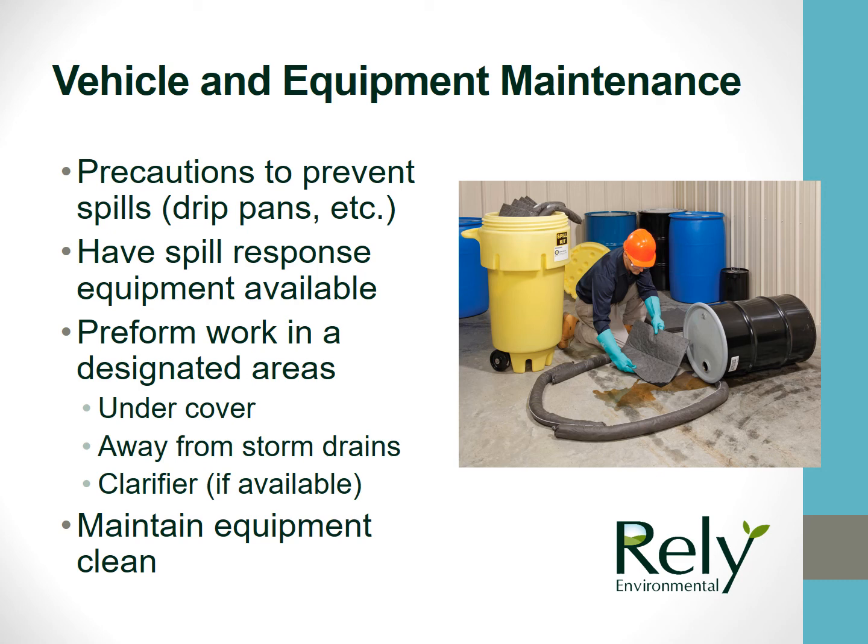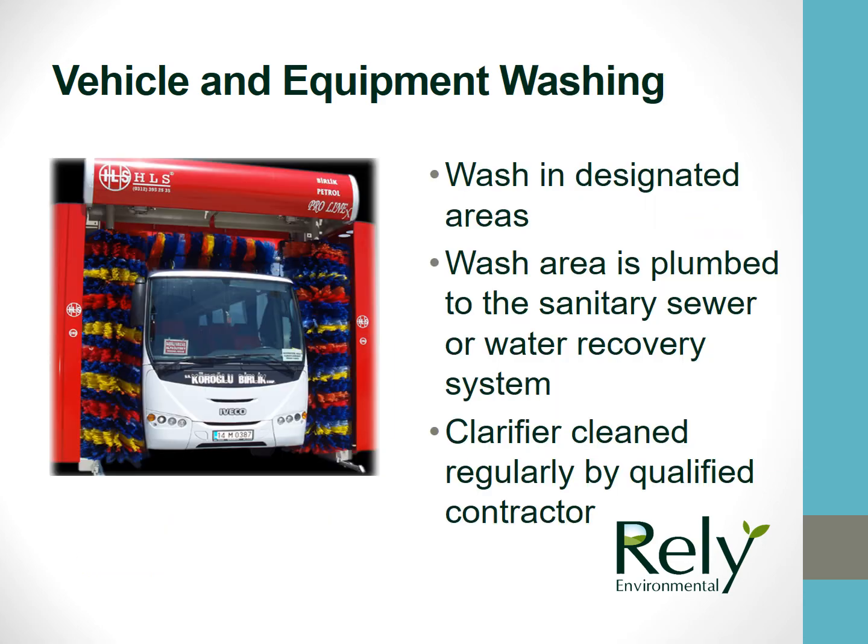Having a clarifier would be ideal if available, and have equipment maintained to avoid any buildup of any grease and oil. Vehicle washing must take place in a designated area because the washing area is plumbed to the sanitary sewer or water recovery system. The clarifier is to be cleaned regularly by a qualified contractor.